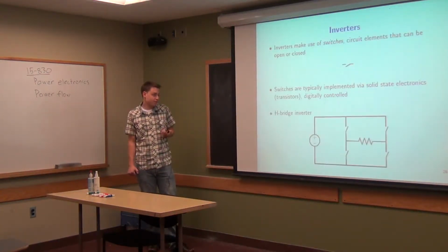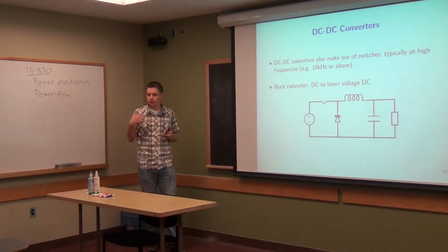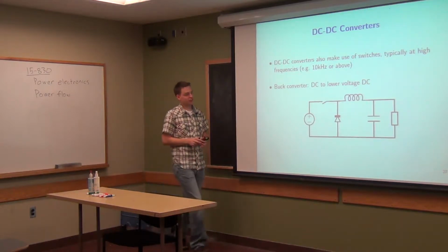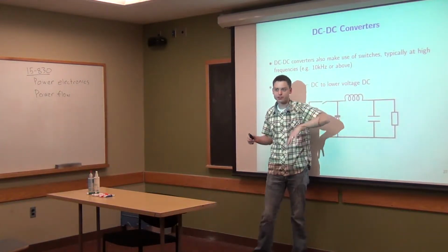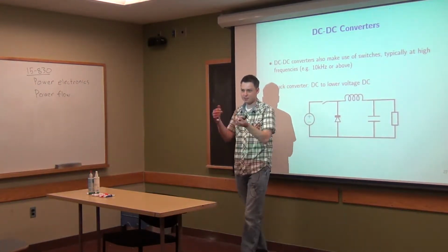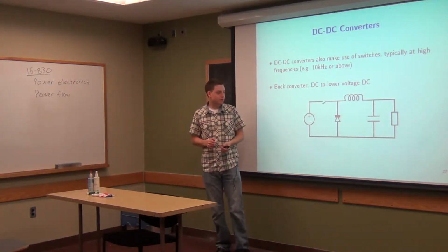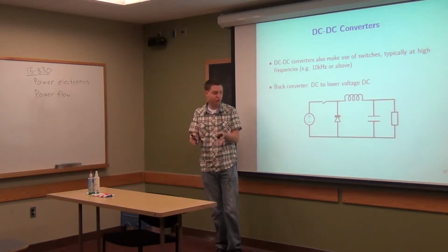And so these are really nice, right? Because we all of a sudden can now do DC-DC conversion just as easily as AC, theoretically. And that's a great thing, because now there's really no good reason that we might want to prefer AC power over DC. I mean, there are other reasons. You'll see the efficiency of these things often, for the same efficiency, they might have to be more expensive, especially at high powers. These switches here are not quite as easy to manufacture as a big magnet if they have to have massive amounts of power going through them. But at least conceptually, we can do the same thing for DC as we did for AC.